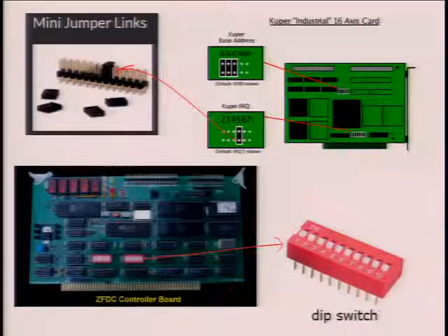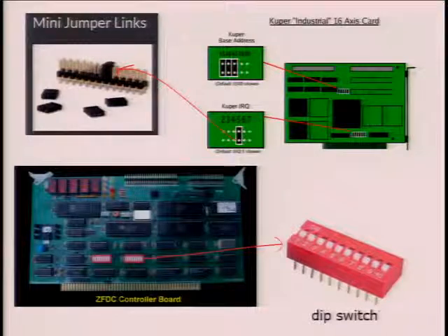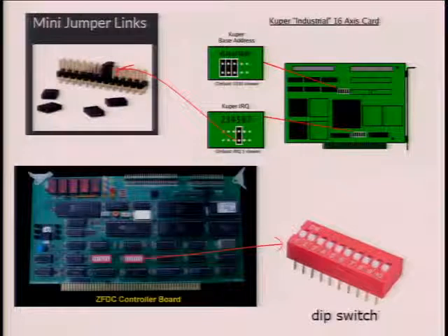Assuming you set the card to a number similar to the existing card, we call these two cards clashing with each other. Most likely, you will never be able to bring up the system. The worst case is you add in another card and set the interrupt number or the memory range similar to your graphic card. Then that's it.